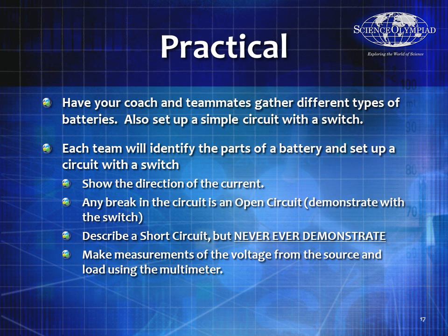Describe what a short circuit would be, but never ever demonstrate it because it's dangerous. And then make measurements with the multimeter so you can measure all the voltages. Remember, if you're measuring the resistance, you quite often have to remove at least part of the element so that you don't accidentally measure the resistance while it's energized or while it's in parallel with something else.